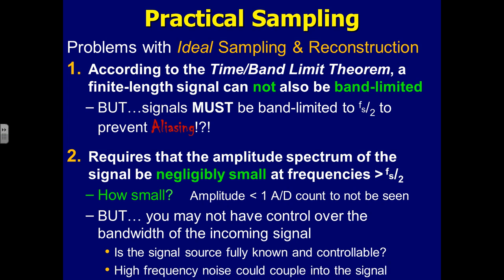And even if we do know the frequency spectrum of the signals coming in, we might also couple in unintended high frequencies into our signals. And if that happens, that high frequency noise will alias and mess up our digitized signal.